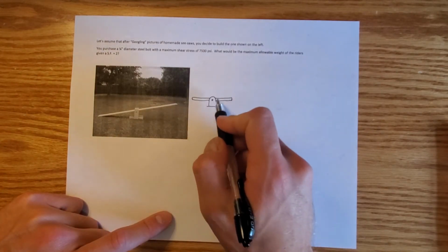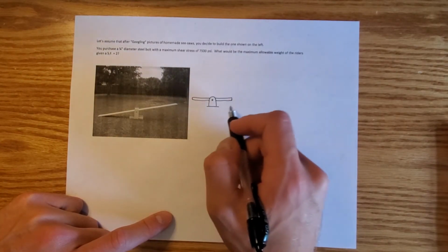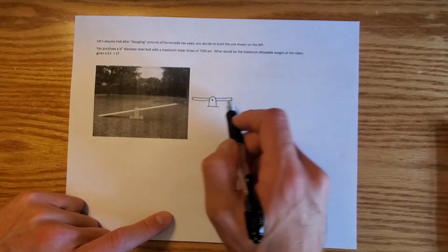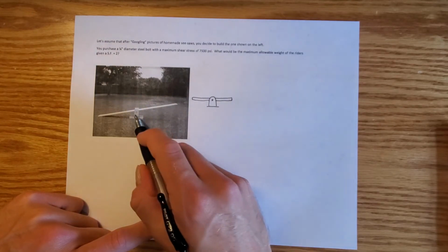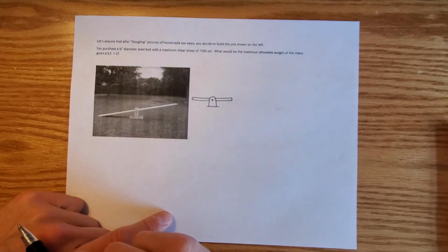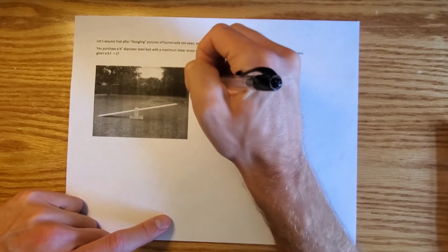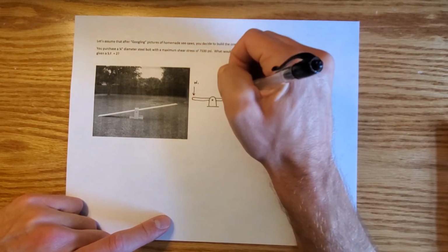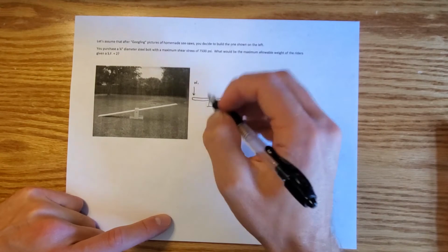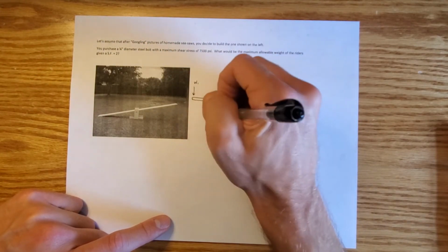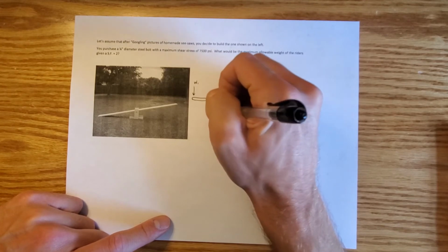So here I've drawn a little tiny rinky-dink free body diagram of our seesaw. We can see that it's held together by a pin. We've got our piece of wood right there. That's kind of your pin right there. And what we know is going to happen is we're going to have the weight of person 1, the weight of person 2. And because it's a pin, we're going to have two reaction forces. We're going to have RAY and then RAX, reactions.